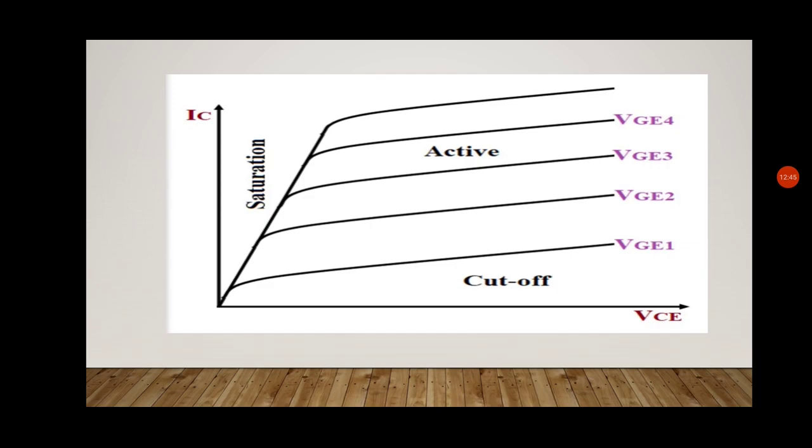Now the main advantages of using the IGBT over other types of transistor device are its high voltage capability, low on resistance, ease of drive, relatively fast switching speeds, and zero gate drive current, which makes it a good choice for moderate speed, high voltage applications such as in PWM, variable speed control, SMPS, or solar power DC-AC inverters and frequency converters. So this is where we can end the video today.